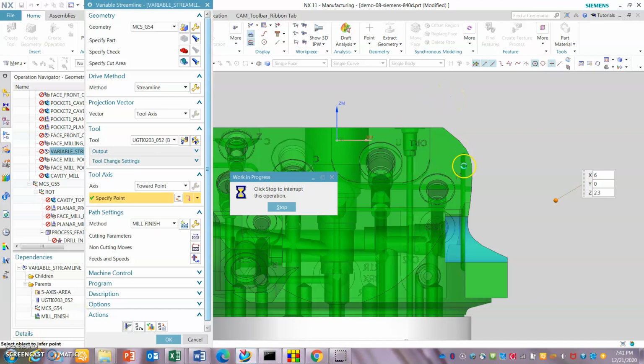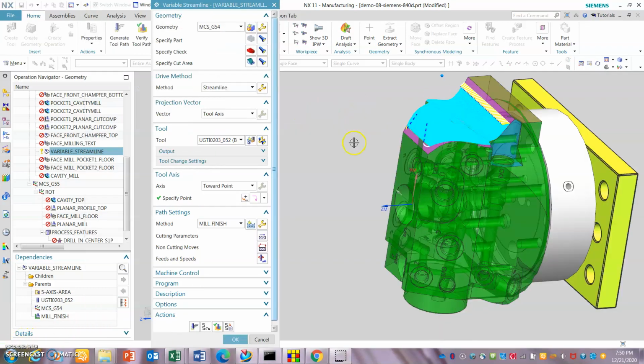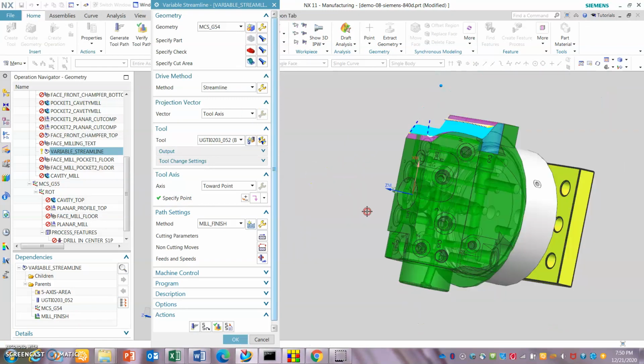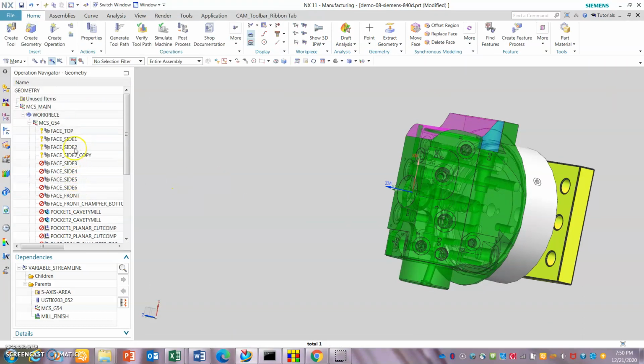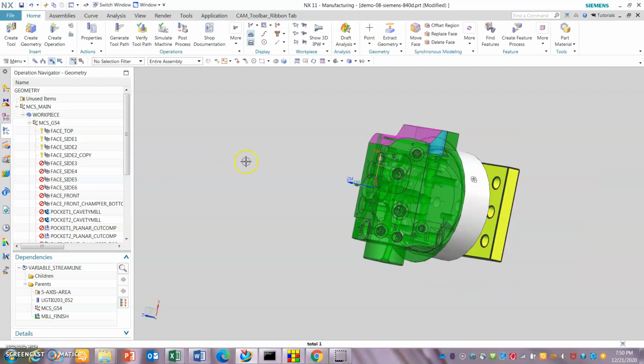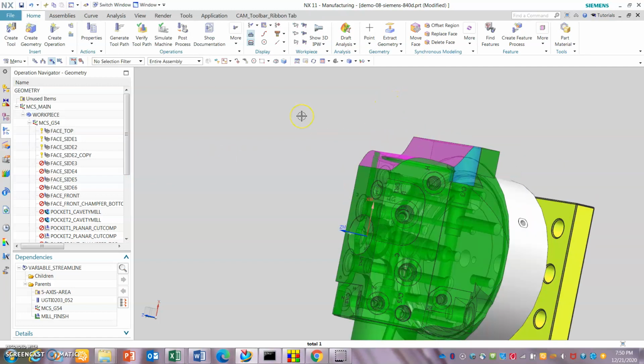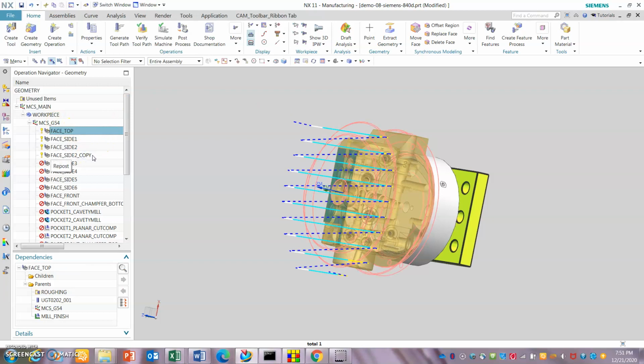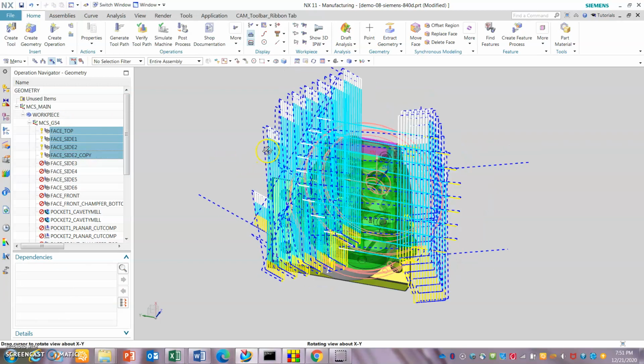So let it come and the tool axis. Okay, now we have an example of a 5-axis toolpath to cut out this surface. Now we'll generate all that we needed for regular planar milling, 3D using 3D coordinate rotation, and also G43.4 or cycle 800 tool orientation, which we had to switch off with the transformation off. Let's make sure that we have all the examples we need right now.